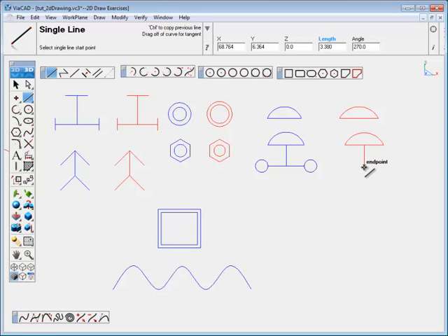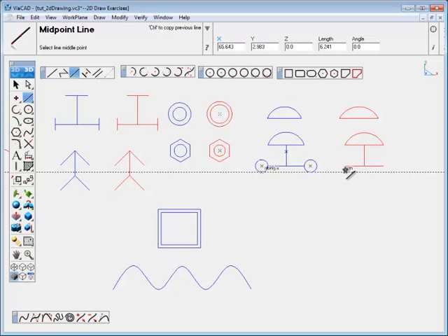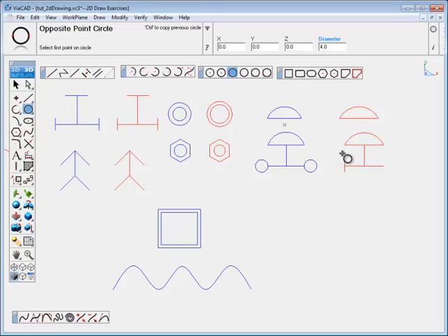Now we're going to use alignment using those two endpoints of the above line as reference points to align to. Now we'll set a circle by defining a line as kind of a construction line, and then we'll snap to its two endpoints. We're doing this just to give you ideas of different ways to construct.